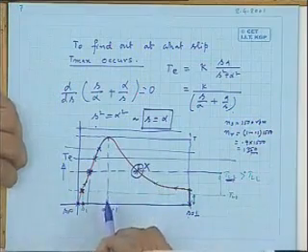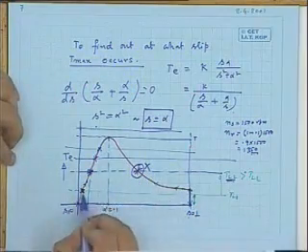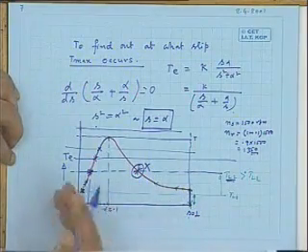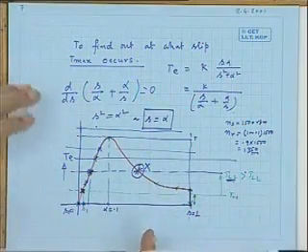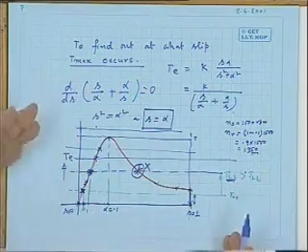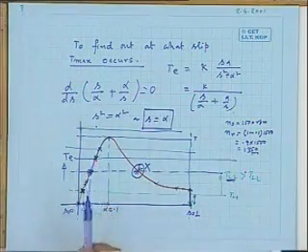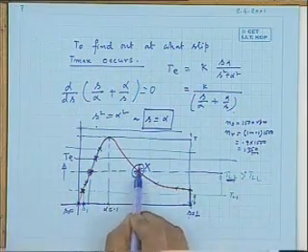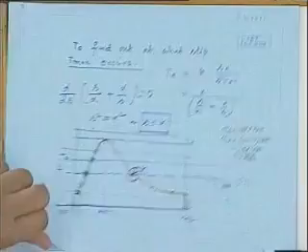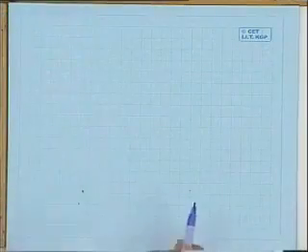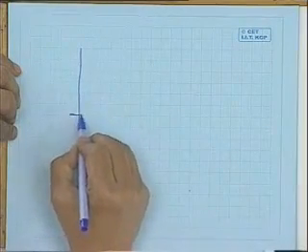But we will explain right now that at this operating point the machine cannot run steadily. It is only these operating points, the point of intersection of the load torque line with the stable portion of the TS curve, that will give you a stable operating point. These other points, it can easily be shown, are unstable. This can be easily explained.